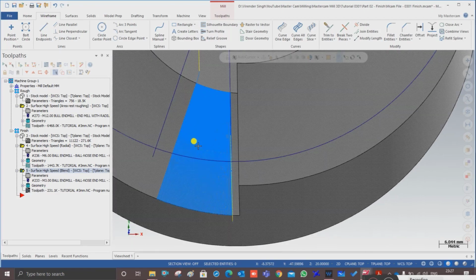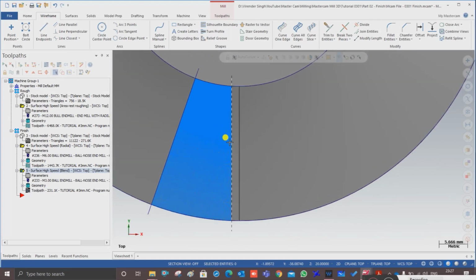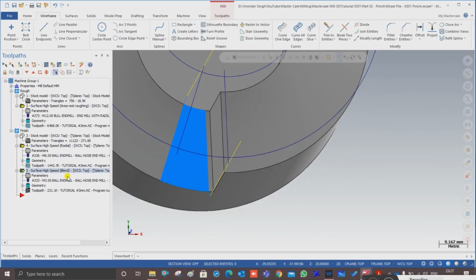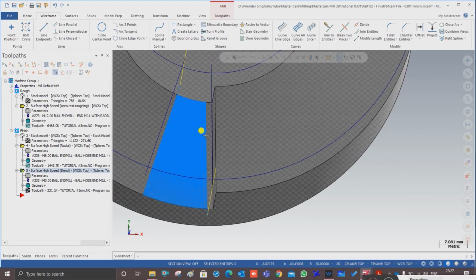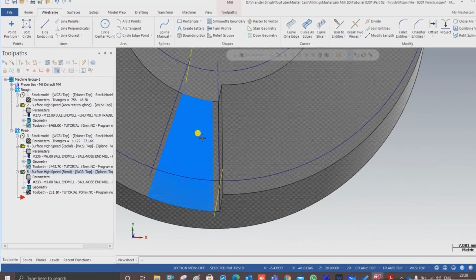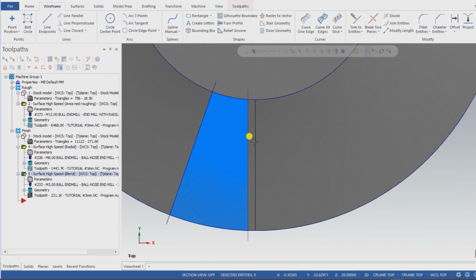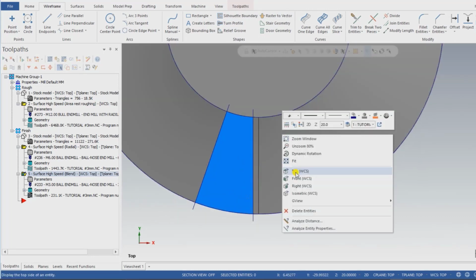The next step that I also want to explain is that I chose an offset of 1.5 mm. Let me show you why I offset 1.5 mm: because I selected a 3 mm ball nose tool. My 3 mm ball nose is touching at the bottom portion, and the corner radius of a 3 mm ball nose is 1.5 mm. That's why I offset it when I select the 3 mm ball nose. I offset 1.5 mm for the corner radius of the toolpath.